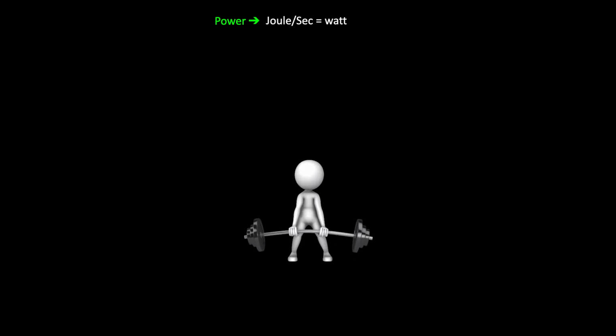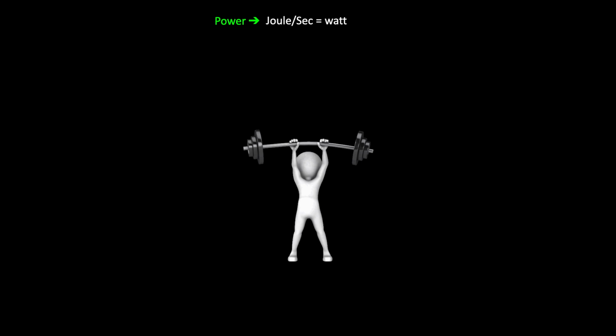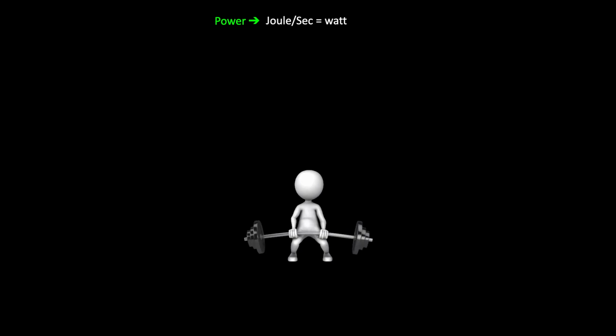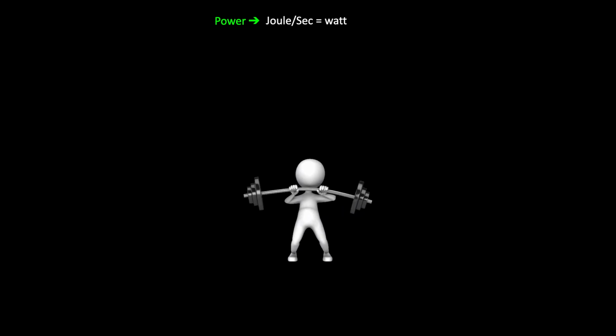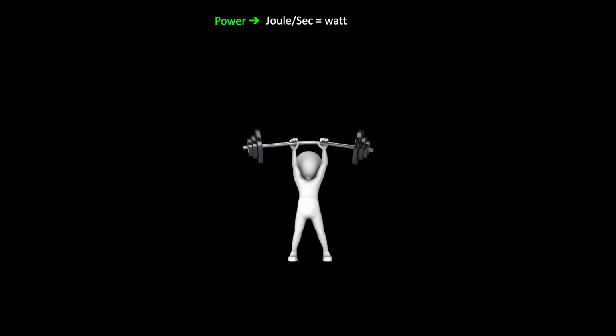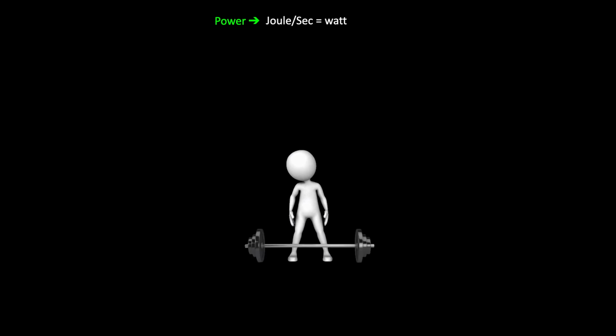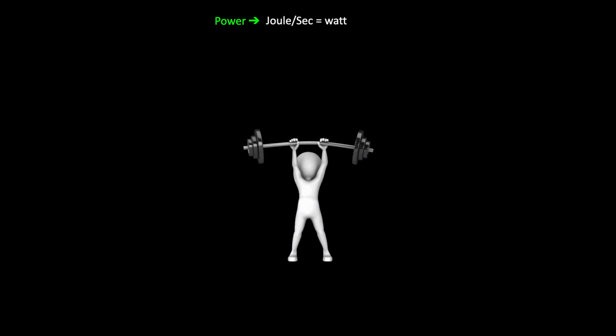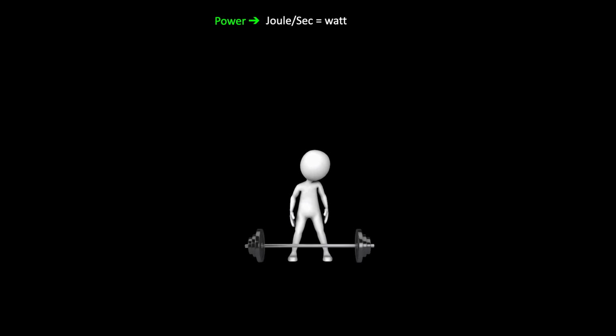If we watch the lift, we see that the speed of the lift is not consistent, regardless of whether the lift is completed in 3 or 1 seconds. Some of the lift is completed faster or slower than other parts, which means the power delivered will vary. So if we use the total time for the lift in our equation, the 1 or the 3 seconds, we define the power delivered as average power.